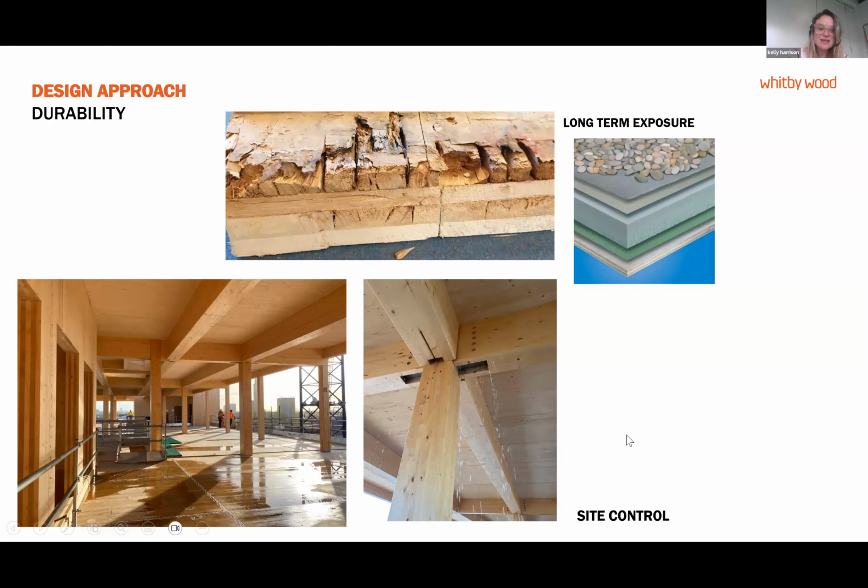So there's little things like that. It will be part of a water management plan from the subcontractor, which you should always ask to see before they start on site. Which is very common now. The major subcontractors in the UK do that as standard, but if you've got a smaller outfit, or a main contractor doing it for the first time and they're not aware of it, you need to make sure you're asking for that as the engineers as part of the site phase of works. But as long as that's all in place and the building can breathe, then you can get around the site phase.